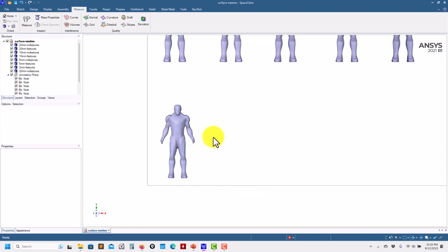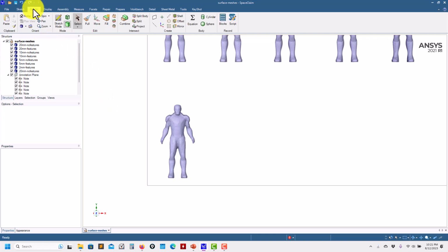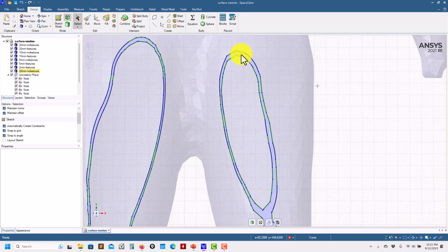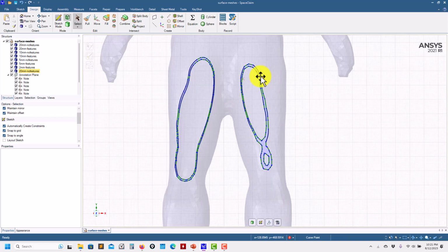Everything has been scaled, but it's also important to talk about the mass that we're using. We know that we need to generate that lift, but also consider stability and so on. What is interesting here is that this STL has zero thickness. After scaling, let me put a plane there and see that I added thickness. I make another assumption: 2 millimeter thickness of the armor material. Who knows, it might be true, it might not. I think 1 millimeter is too thin, and 2 millimeters seems realistic. Some parts probably will be thicker than that.